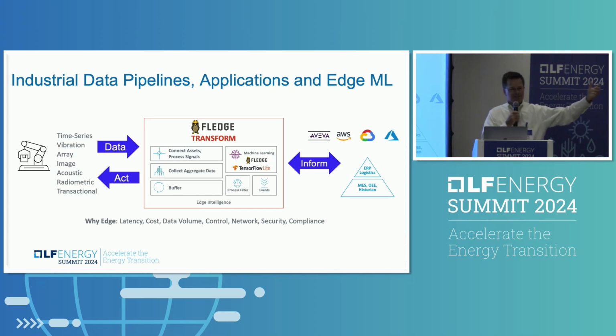So I can take this vibration data, signal process it with FFT, convert it to a common JSON, and then convert that into how you send it to Amazon, how you send it to Google, how you send it to a PI server, how you send it to eDNA, how you send it to your IBM maintenance system. But not only that, you can create multiple pipelines to multiple destinations from a single target.